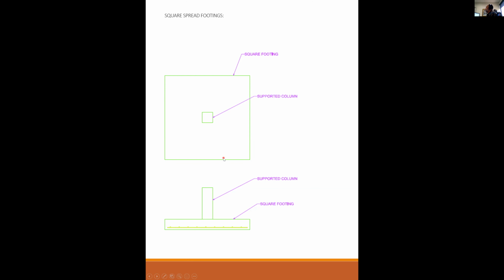And on a square footing, it's completely arbitrary which is going which way. In fact, you have no idea which way the contractor is going to be laying that steel. So you have to make your worst assumption. If d is less for the steel on top than it is for the steel on bottom, then we're going to be conservative and just assume that we're designing the steel on top.